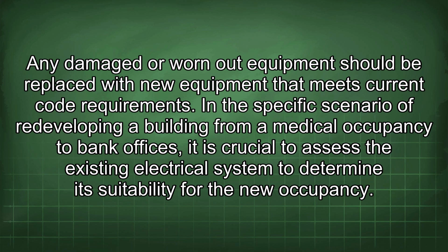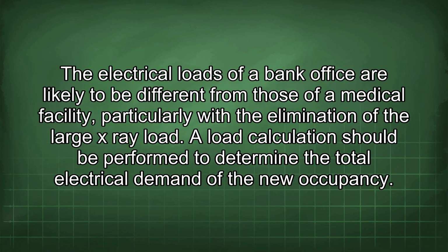In a specific scenario of redeveloping a building from a medical occupancy to bank offices, it is crucial to assess the existing electrical system to determine its suitability for the new occupancy. The electrical loads of a bank office are likely to be different from those of a medical facility, particularly with the elimination of the large X-ray load.